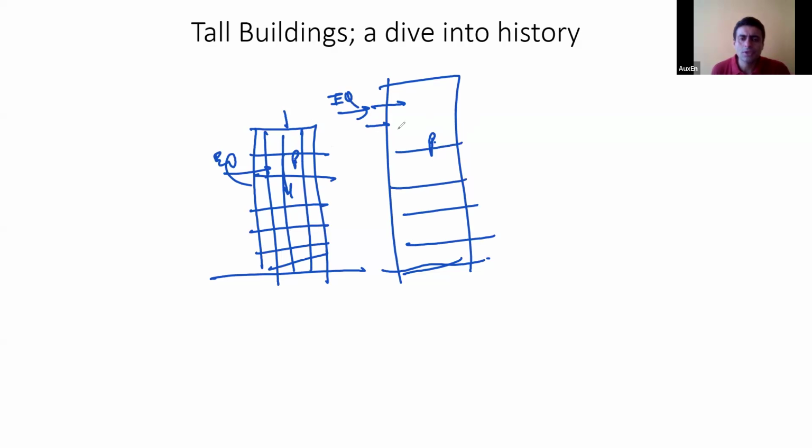But when it's a G+60 story building, a moment frame system is not working for you. That means you're not able to control the drifts and deformations, and the lateral acceleration is causing a problem. So then you may have to think about other scenarios. That's when you'll understand that this building behavior is slightly different from a regular building behavior.